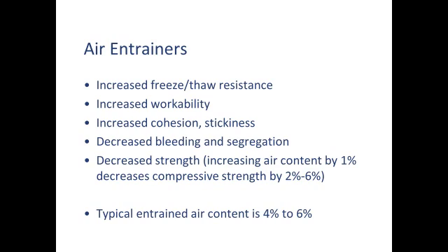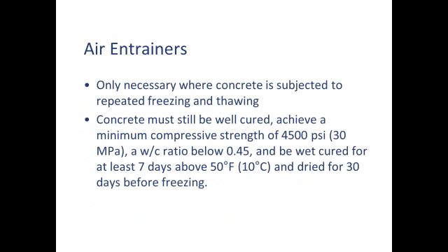There is a penalty. You do lose some strength with air entrained concrete. Perhaps at 5% air entrained content, you might lose 10 to 25% of your compressive strength because of that. Now that sounds pretty extreme, but if we're already making super strong concrete, we can afford to lose that and not have any downsides. I suspect that it's more likely on the low end, not the high end. I wouldn't worry about it too much, but air entrained concrete always is a little bit weaker than non-air entrained concrete.